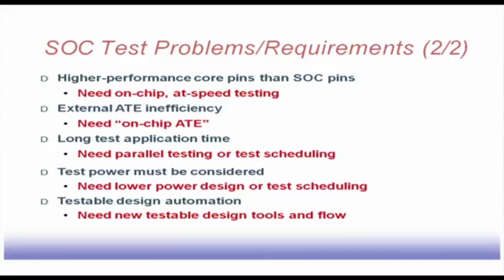Then long test application time. So, what has happened in the SOC design paradigm is that you have so many components to be tested. Now, the IP vendors have provided us with a set of test vectors for each of the cores. Now, if this entire system was designed by a single group or single person, then they could have filtered out the test patterns, or they could have found the test patterns which can test a number of faults in different components. So, that way there may be a possibility of doing a compaction of the test set.